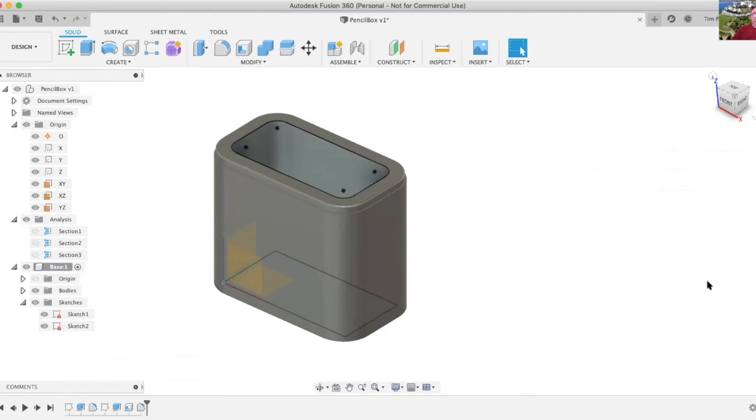Question here, this is Pete. I'm seeing four black dots. What do those mean? Those are the center points for the arcs in the drawing in that sketch. That's part of the sketch. If I turn the sketch off, those will go away. I see. Normally, by default, Fusion 360 turns the sketches off when we're not using them.